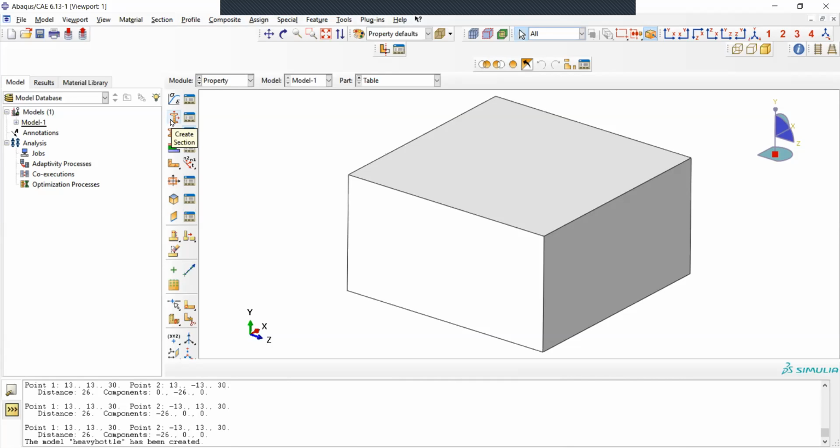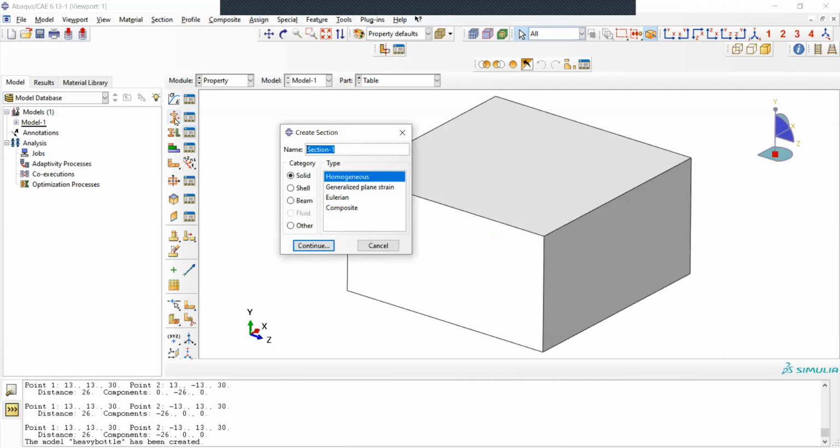And then I use that information that the material is for a 3D body. And then I tell the software that this material for 3D body is for the specific body. So I create a section and then I assign the section. I will re-explain it along the way. So I create a section.